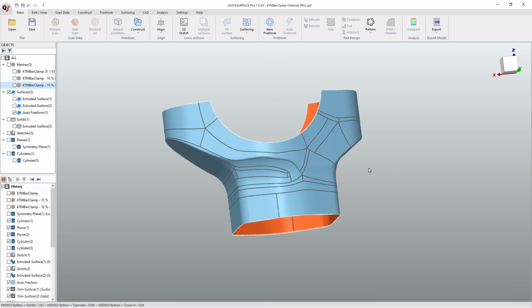We have access to more CAD tools. We can do things like trim and cut. Those aren't options in LITE. We can build all sorts of primitives and surfaces in LITE, but then we have to export all of those as intermediate CAD data and work with them in another program like Fusion. We can also do things like extrude and snap to a mesh.